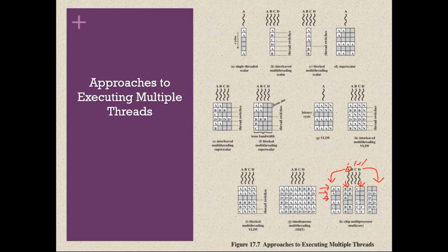But as of now, only thread A is for processor 1, so it can't do anything. During the next clock cycle, it tries to fetch two independent instructions from thread A, and it got them. During the next, there are no such instructions. Then during the last clock cycle it got two independent instructions from thread A, and so on. Similarly for the other processors also.